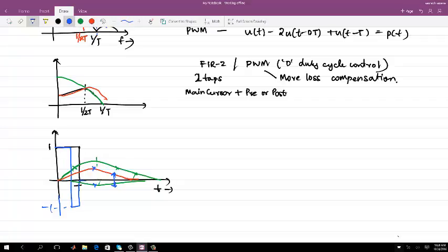So in terms of frequency response, with PWM we are introducing more high frequency content. Does the picture become clear in both frequency domain and time domain? In the time domain, you see superposition of a positive and negative pulse. In the frequency domain, you see more transitions within the same amount of time, so higher frequency.